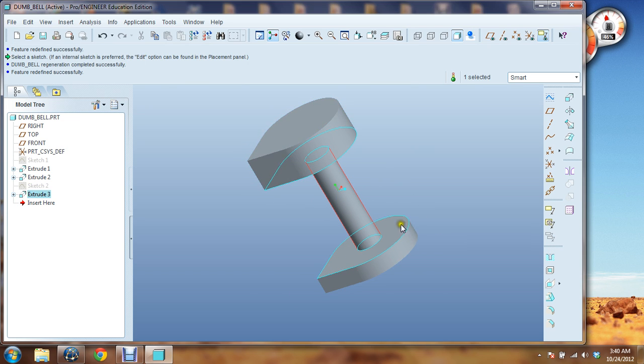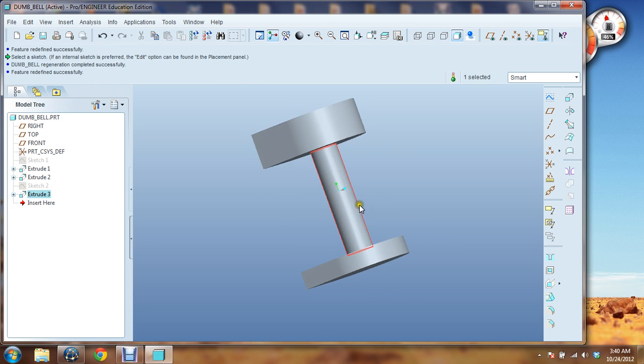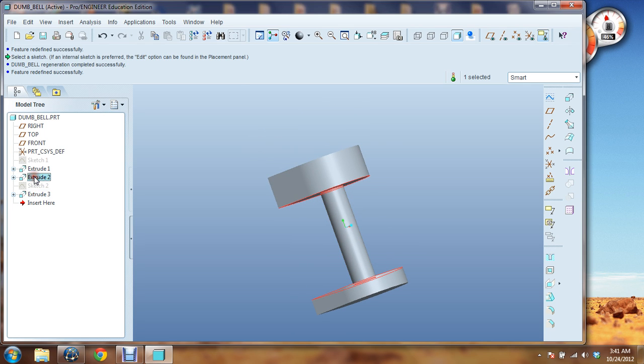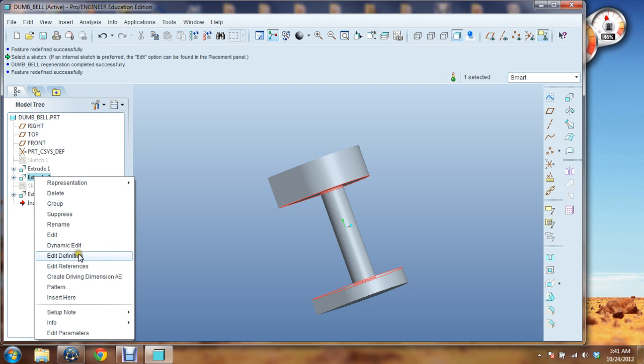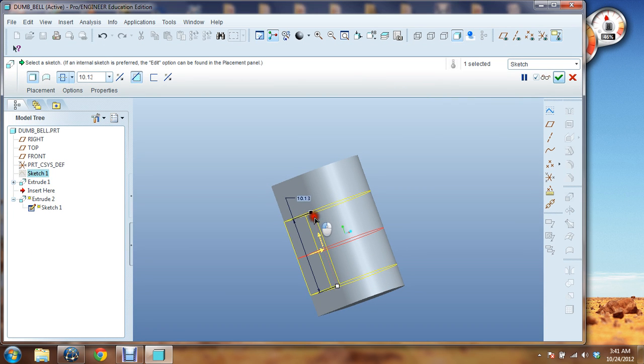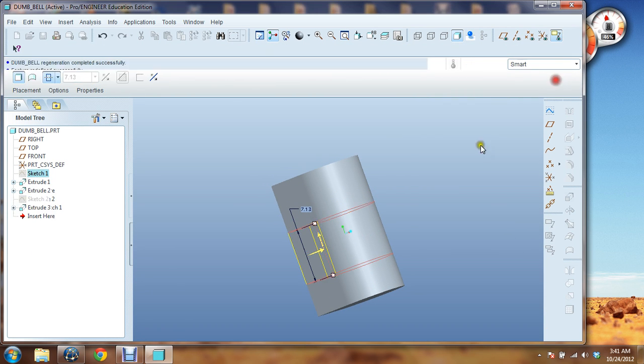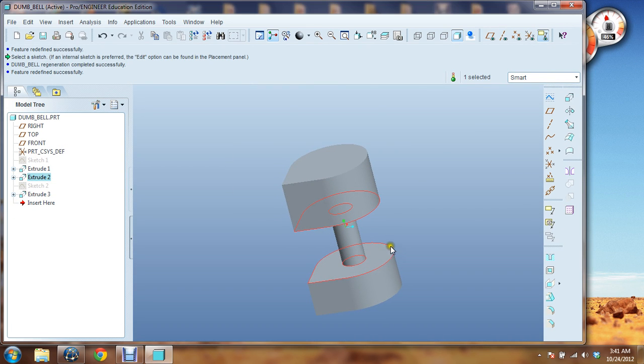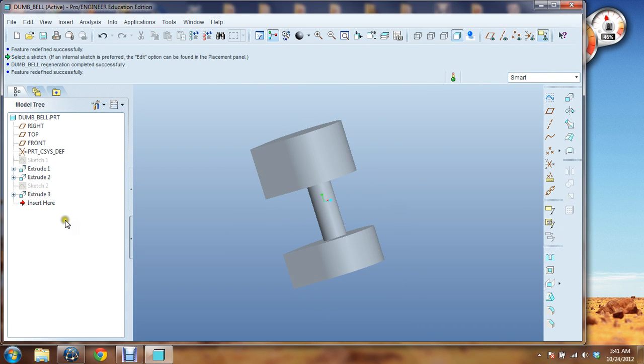And something else I wanted to point out is when we cut this, you notice that sketch, we only didn't meet one side. The other side stayed exactly where it was supposed to be, because when that surface moved, that sketch moved. And that's kind of where design intent comes into play. We basically made this model with the intention of being able to modify it. So if I went back into our cut extrude, now to edit it, now to shrink it down, everything is exactly as it should be.